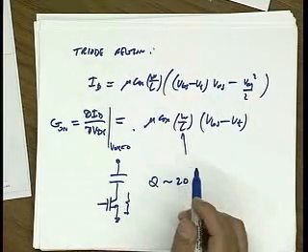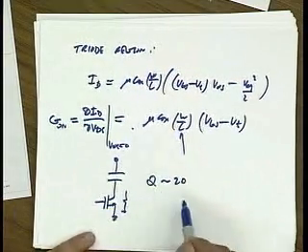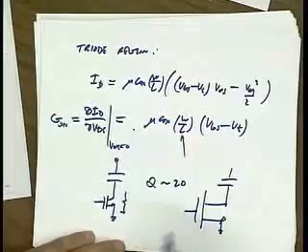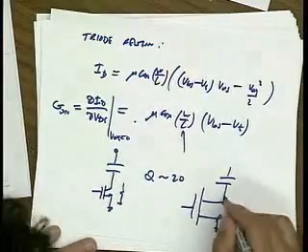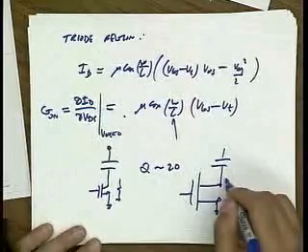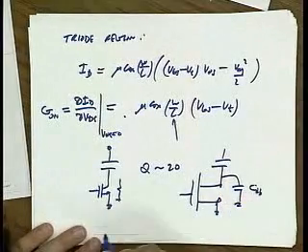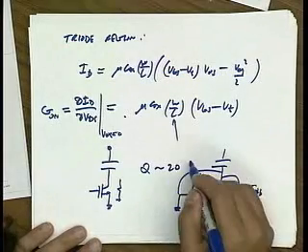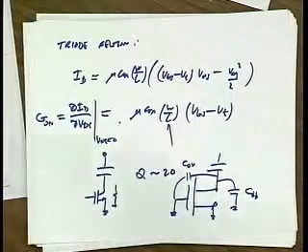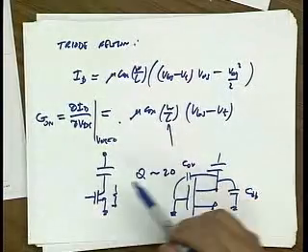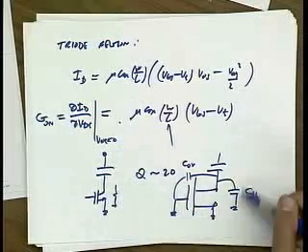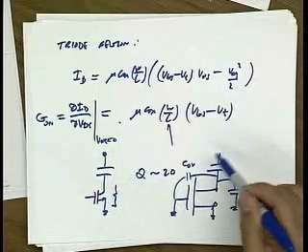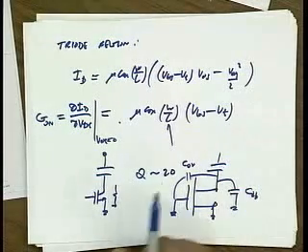Okay. Now you might say, big deal, just make the device bigger, right? Make W huge. So why not just make a huge device? Well, the reason is that this device has parasitics. So there's C drain to bulk parasitics here. When I turn this off, let's say I ground this node. And there's also this big overlap capacitance. And so it's kind of hard to turn this capacitor off. I can turn it on, right? But I can't turn it off, because these bulk capacitors, these parasitic capacitors, should be much smaller than this capacitor. Otherwise, the circuit doesn't work.